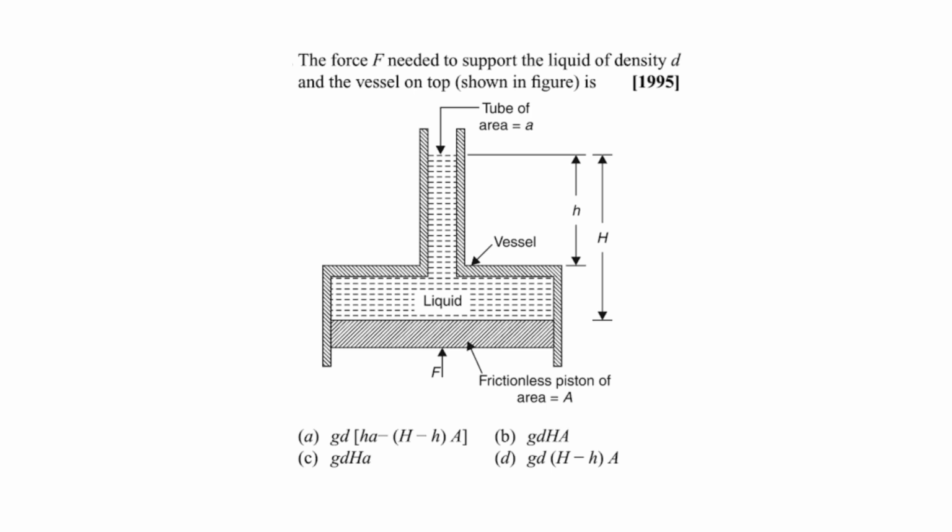So you only need to find out the force that you need to apply on the area capital A. And to know the force which is acting on any particular area, simply apply the hydrostatic law as I told in the video. The reason I explained this hydrostatic paradox was that some of the students can get confused about why not take the whole weight, because if you equate the weight of the liquid to the force acting on the bottom piston, you won't get the correct answer.